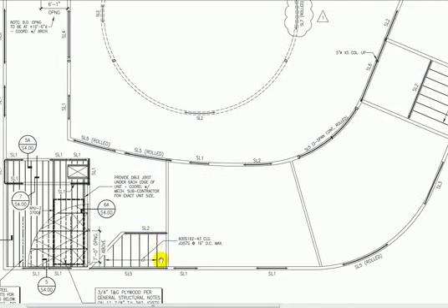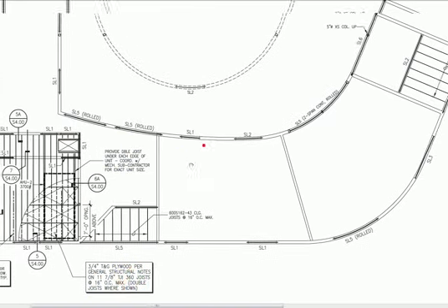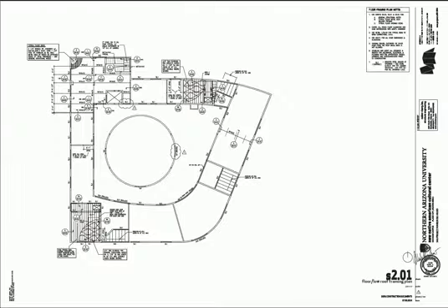Go over here. Looks like we have some more metal stud joists and tongue and groove over some 11, almost 12-inch TJIs. So this just looks like a little mezzanine plan here. So we got a bunch of different construction materials. We've got rolled structural steel with metal deck and concrete. We have wood TJIs or truss joists with plywood, and we have metal studs, and we have steel lintels.